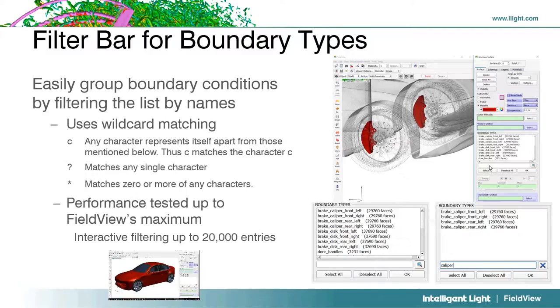So you could import the CAD geometry and append it, as I said, and it often has more details, so it also makes for better rendering. FieldView has the ability to rotate, scale, translate a data set compared to the other one, so you could also put it back into position if it doesn't really match the flow field. And then from the CAD, you will have all the details you need for applying different materials.